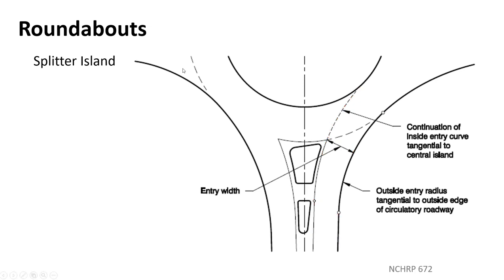All right. This time, actually arc it more back here, and then have this become a tangent straight out until it intersects that island. Because this assumes that cars come up here and stop, they're going to continue an arced path, following that arc out into the road. Later on they said it may be better to actually draw that straight out, because people are probably going to try to go more straight ahead. So you curve them more back here. You're going to curve them in this region and not continue to curve through that.